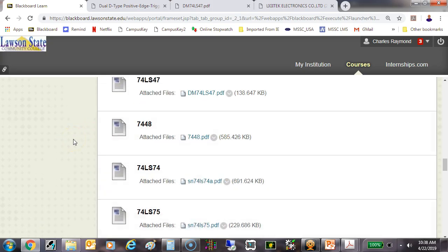So the question was, what would we use to convert an octal number into a binary number? Some of y'all said a 74138. That's binary to octal. That's not octal to binary. Some of y'all said a 7447, which is a binary to 7-segment decoder. And the question was, what's required to convert an octal number into a binary number? So that's not a decoder, that's an encoder, right?